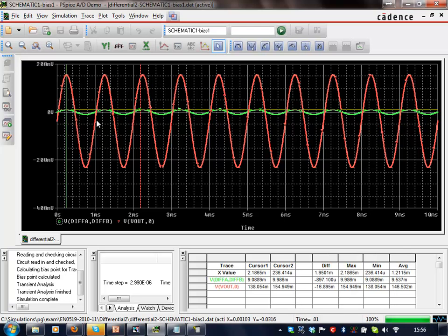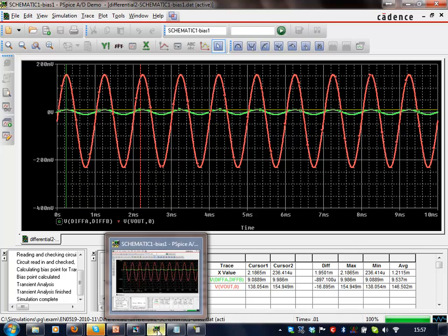Okay, now there is a small DC shift here which we haven't moved out, which is fine, because when we calculate the difference signal, we'll only look at the peaks and the troughs. So we'll actually get rid of any DC component, and then we can extract the DC component later when we optimize. So, looking at the peak and the trough of those two waveforms, here's how we can do that.